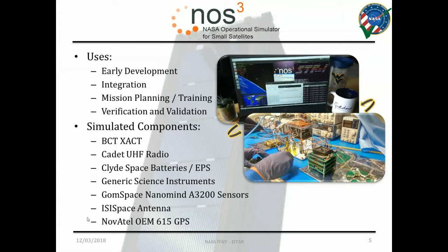And I have down here a list of components that we created hardware simulators for within the NOS3 infrastructure. Blue Canyon's XACT ADCS system. We created one for the Cadet UHF radio, some for the batteries that we're using, and then some generic science instruments.